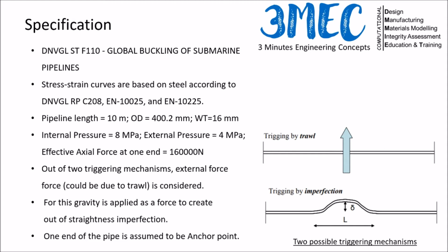I am also assuming the effective axial force, which is an important driving force in the pipeline stability or deformation. That is the force which is acting along the axial direction of the pipeline. It is generally in compression.